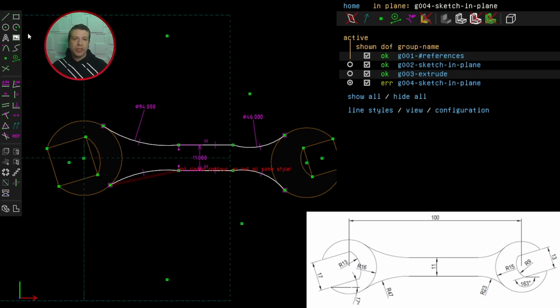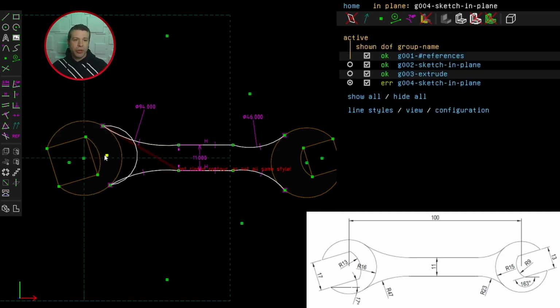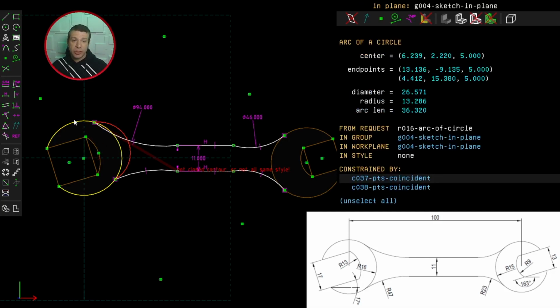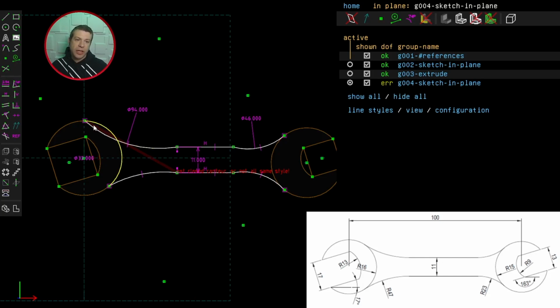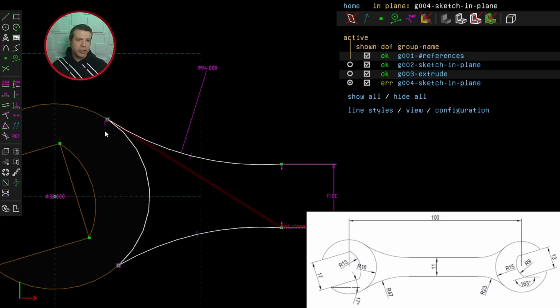And the way to do it is clicking here again on the arc tool, and then clicking on these 2 points. I can constrain the diameter of this arc now to be the same as this one. And by doing that, you see that they're now overlaid over each other. That I've been able to overlay this arc over the previous one. And now I can use that tool to make sure that this arc is tangent to this one by selecting them both and clicking here. And you can see there's a T here to say that these 2 arcs are now tangents to each other.